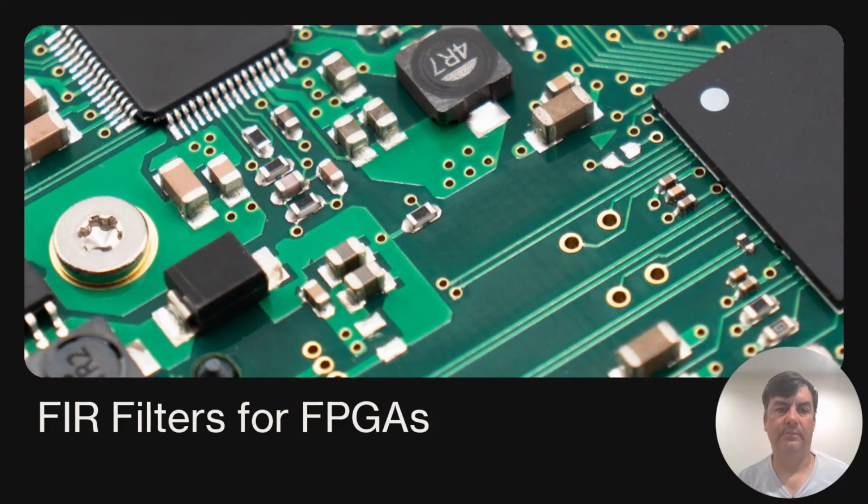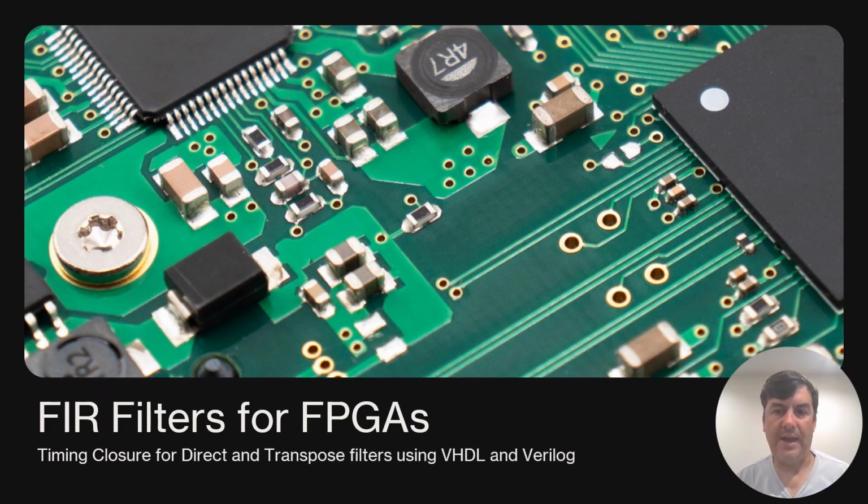implement them on FPGAs. We'll explore both the direct form and the transpose form FIR filter architectures using VHDL and Verilog. I'll also show how timing issues arise with the direct form as the number of taps increases, and how the transpose form solves that problem. Finally, I'll briefly touch on Vivado's FIR compiler IP core. FIR filters for FPGAs, timing closure for direct and transpose filters using VHDL and Verilog.